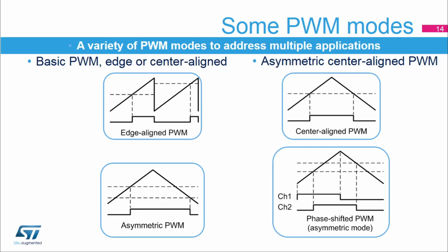When multiple PWM waveforms are generated by the same counter, all falling edges occur at the same time, hence the term edge-aligned. On the contrary, the rising and falling edges of center-aligned PWMs are not synchronized with the counter rollover, so that switching time varies with the duty cycle value. This is achieved by programming the counter in up-down mode. This mode is interesting as it spreads the switching noise when multiple PWMs are generated with the same timer.